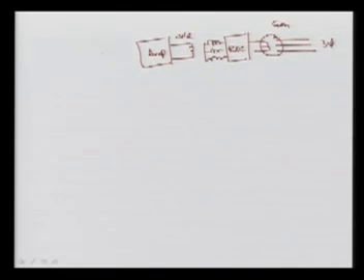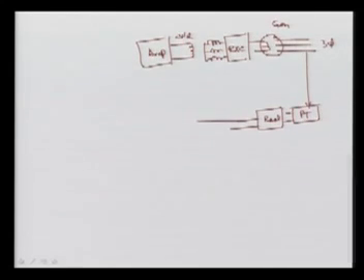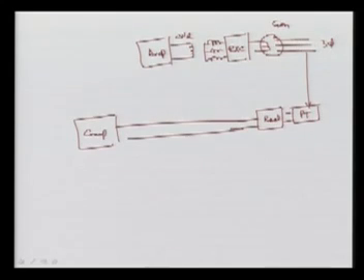Now here we have another part, basically the comparator. Means we measured, again you remember, using the PT, the potential transformer, means we are measuring voltage, and this is given to your rectifier circuit, so we get some DC voltage. This DC voltage is again compared in the comparator with the V reference value, and this gives your change in E, that is the error.